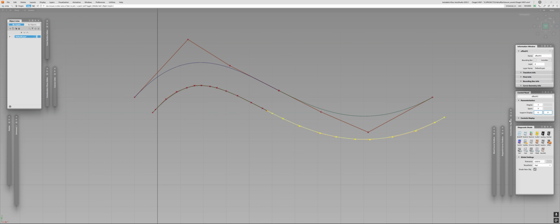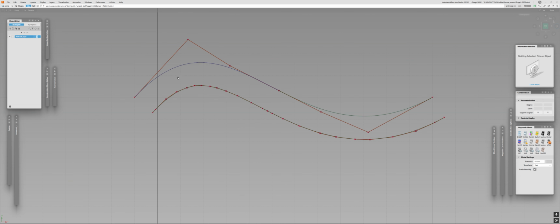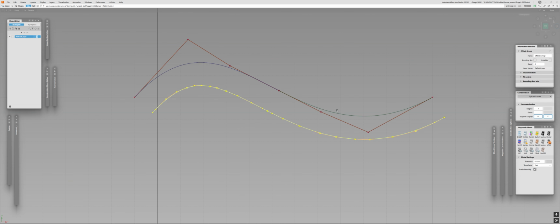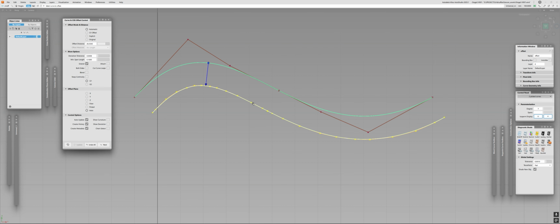And this one has 9 spans. Well, we have a single span of simple curves, just 3 degrees for control vertices. And here we have, for example, 3 degree 11 spans. Now, in this algorithm, the complexity of the curve is defined by the tool, by Alias itself.